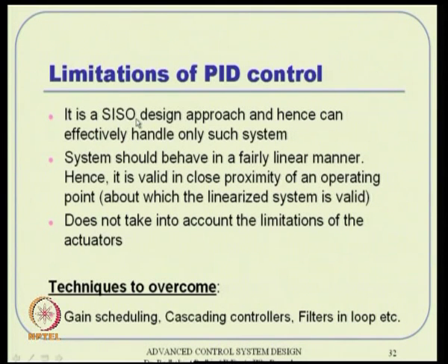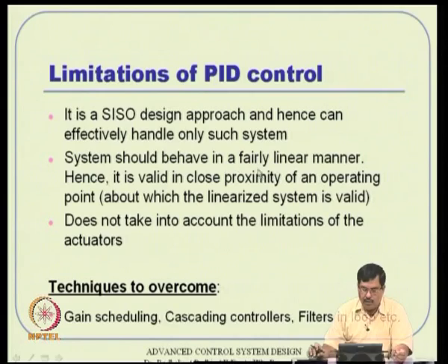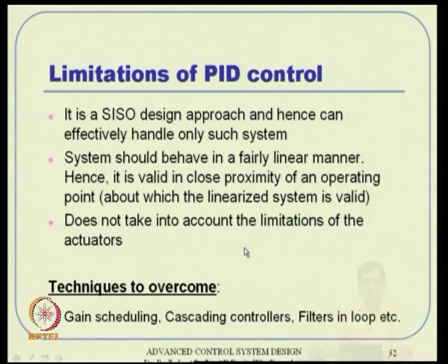It is a SISO design, primarily single input single output, and hence can effectively handle only such systems. If there is a MIMO system, you can have a variety of SISO channels, and then it may or may not be sufficient. And systems should behave in a fairly linear manner. If it is a nonlinear system, there is a problem. Linearity means we should use it in close proximity of some operating point about which we have linearized the system. And obviously, it also does not take into account the limitations of actuators. So, there are various concerns in PID control design. It is a wonderful tool, works in practice, but there are several limitations as well.